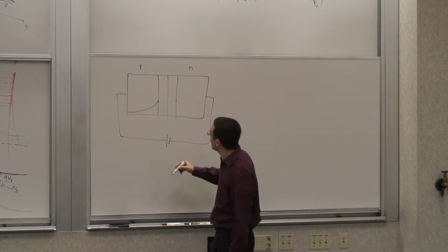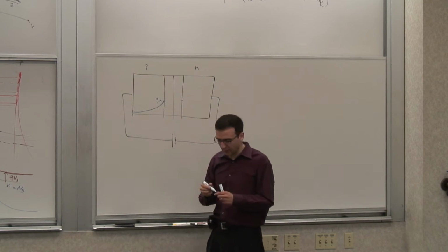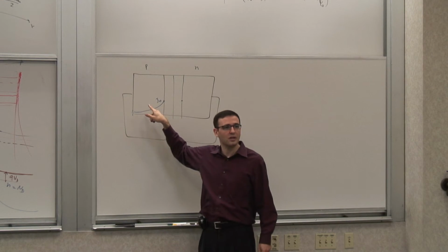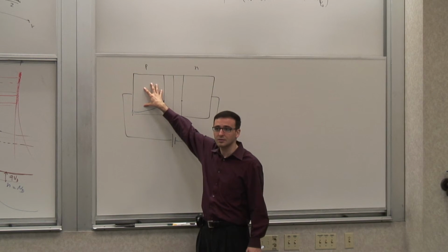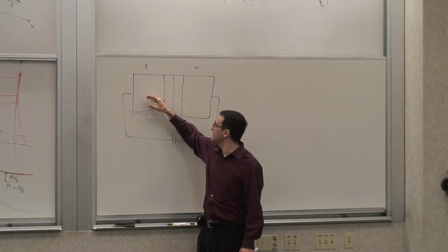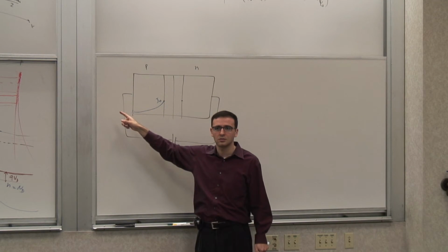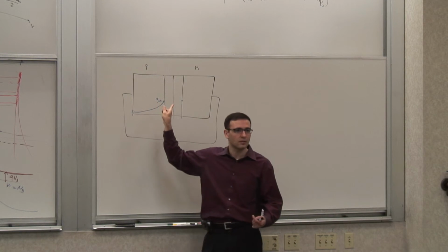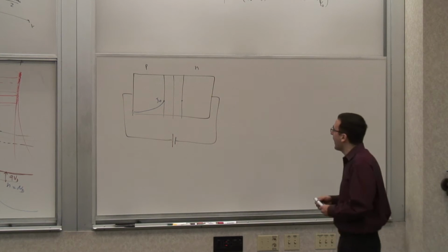And what happens is that you can see that the component of the current carried by the electrons on this side starts dropping. Because the farther you go, there's a higher chance that more of these electrons recombine with the holes that you have plenty of here. And they recombine. And from that point on, the current will be carried by the holes. Because for every hole lost, you have to put another hole in, which corresponds to current flowing in. Now, how about holes?